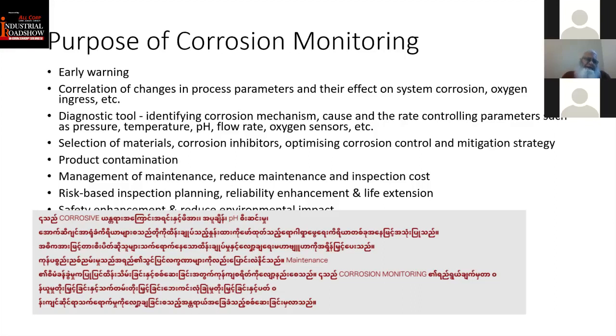Because if you can reduce the corrosion accidents, right, you can also reduce these environmental impacts and you can also enhance the safety. Integrity verification of process piping, pipelines, and fixed assets. Optimize the use of opportunity crude oils in the refinery, because as you change the crude, the corrosive characteristic changes, and corrosion monitoring has to be done for that. As the corrosion characteristic changes, the corrosion rate on monitoring devices will change.